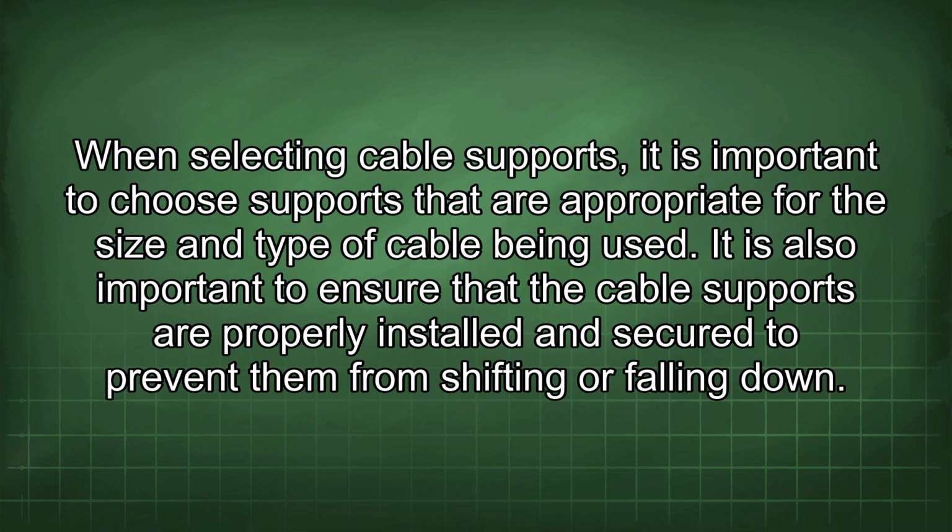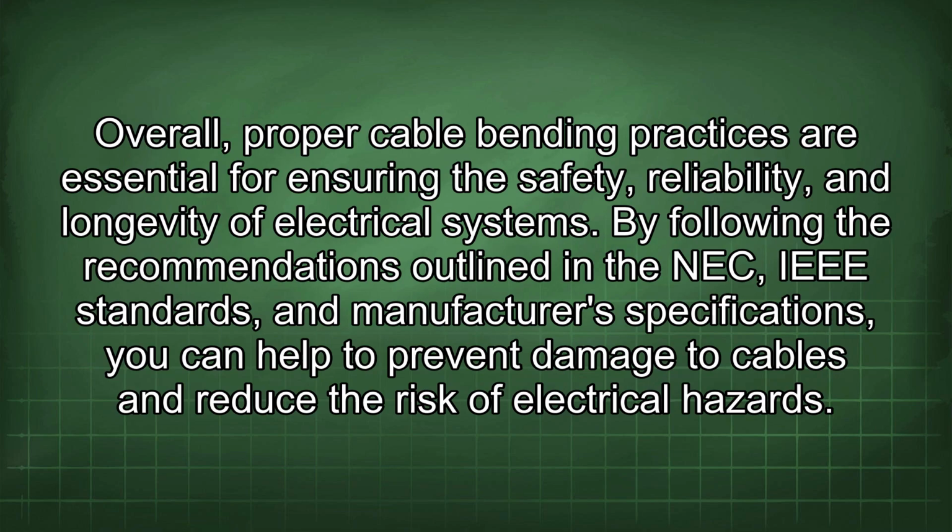When selecting cable supports, it is important to choose supports that are appropriate for the size and type of cable being used. It is also important to ensure that the cable supports are properly installed and secured to prevent them from shifting or falling down. Overall, proper cable bending practices are essential for ensuring the safety, reliability, and longevity of electrical systems. By following the recommendations outlined in the NEC, IEEE standards, and manufacturers' specifications, you can help to prevent damage to cables and reduce the risk of electrical hazards.